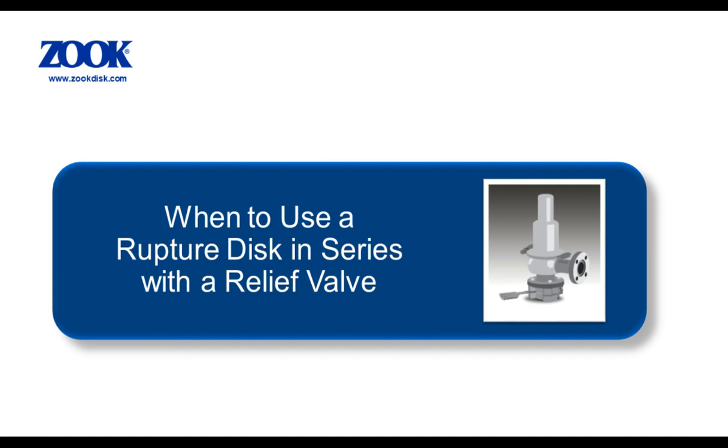Rick mentioned earlier an application that includes a rupture disc device in combination or in series with a pressure relief valve. For this application, the sizing is based on the pressure relief valve capacity. The effect of the upstream rupture disc device is accounted for by applying a default of 0.9 capacity factor, or CCF, to the valve flow capacity to give a conservative relieving capacity for the combination.